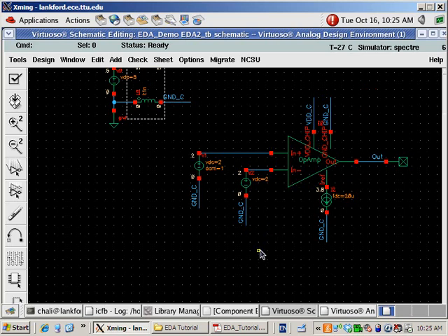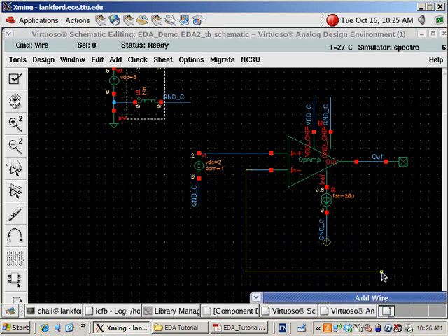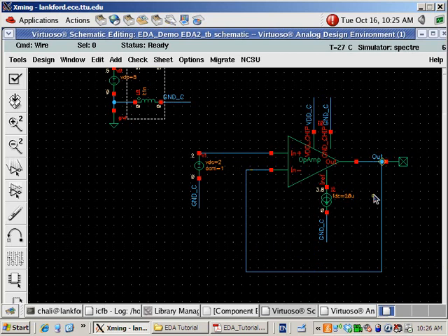Next we have to learn how to compensate for it in a real feedback circuit. So in a real feedback circuit, I'll delete this, and I'll make a connection from the negative input to the output. What is the function of this amplifier right now? From here to here, it's a voltage follower, a buffer, and the gain will be 1.